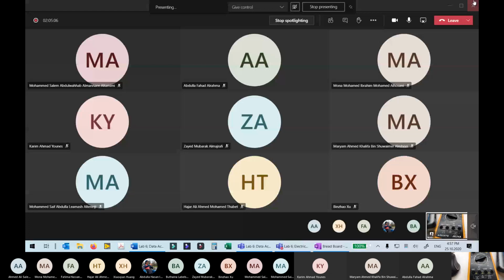On the device dial, what do you need? Voltage DC. You see this symbol? This is voltage DC, and this is voltage AC. Say I want to see if a car battery is fully charged or not.